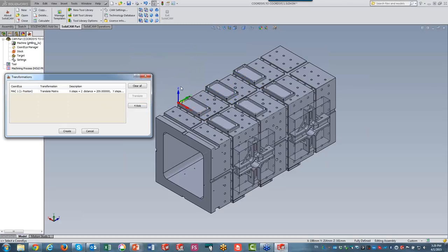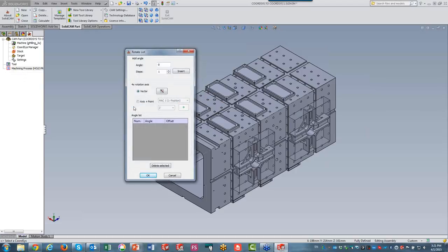Now, besides this, I also want to create these coordinate systems on the flip side as well. So I'll take this entire matrix that I have over here and also do a transform via the fourth axis, where my angle is 180 degrees. I'm going to insert them, and you see it added itself over here. And I can also decide what my angle and my rotation axis vector are.